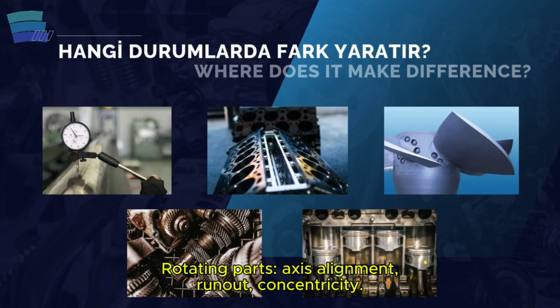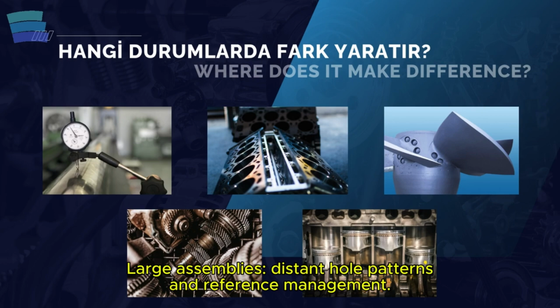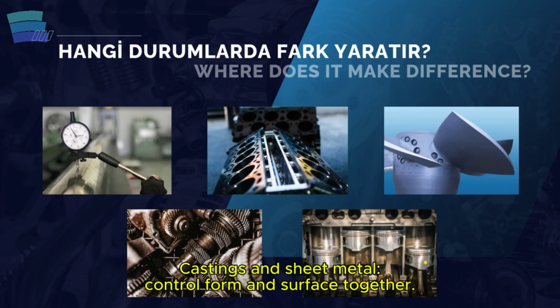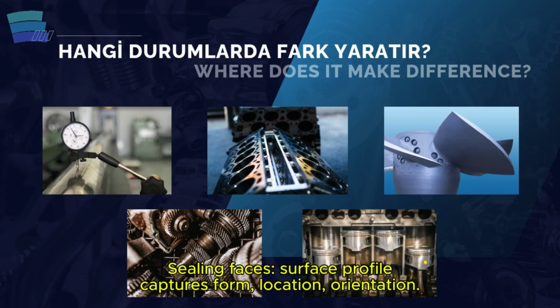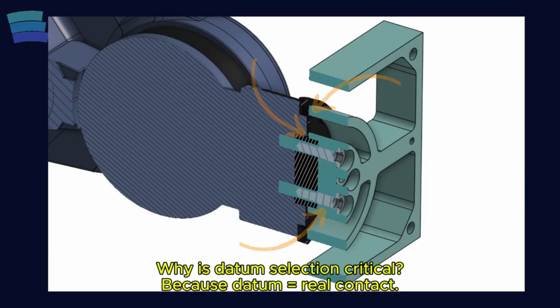Rotating parts. Topics like axis alignment, runout, concentricity. Large assemblies, distant hole patterns, reference management on large components. Castings, forgings, sheet metal, controlling form and surface together. Sealing surfaces. A surface profile control can cover form, location, and orientation all at once.